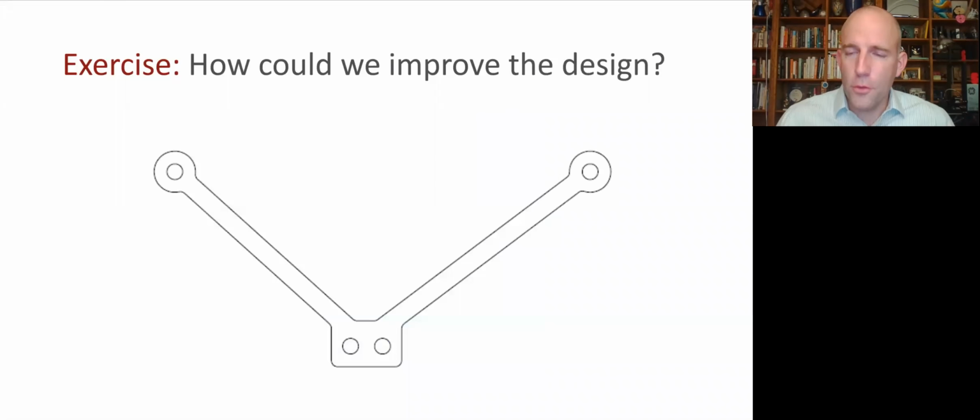So how can we use this information to improve our design? Think about the kind of loading that it actually experiences compared to what we thought at first. And what are the implications for how we could improve this component? And by improve it, I mean, how do we make it stronger for the same mass, or keep the same strength and reduce mass? This is in these sort of mass optimal design problems. And there are two approaches that can work well.